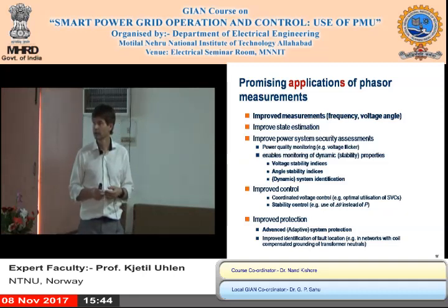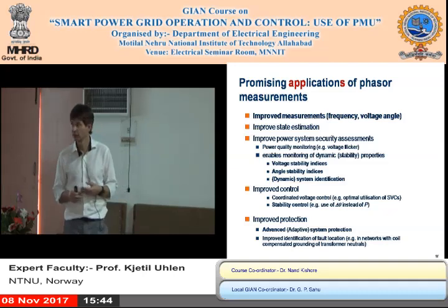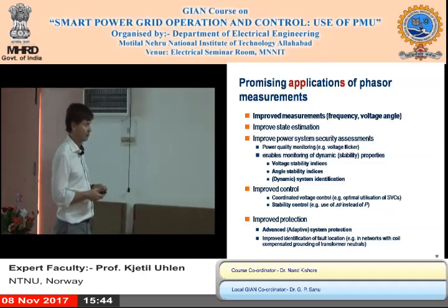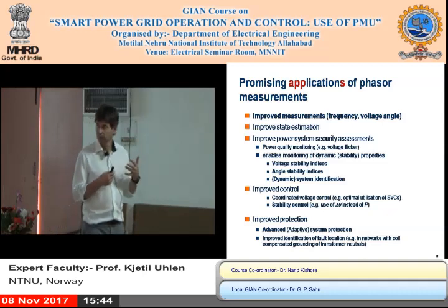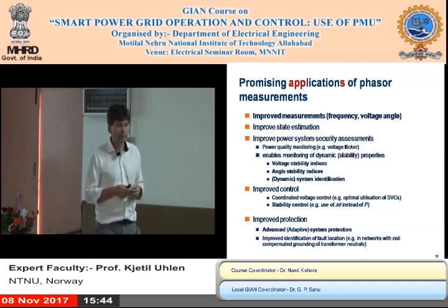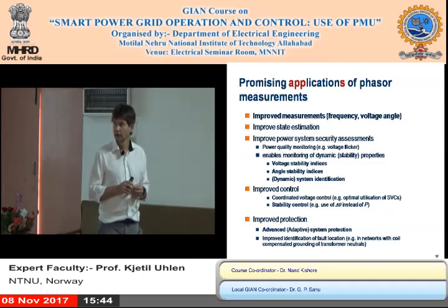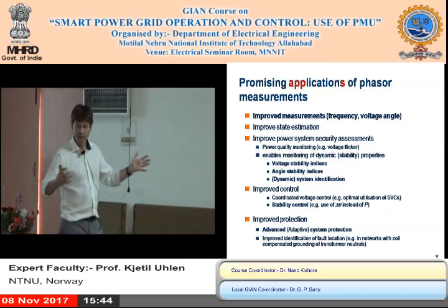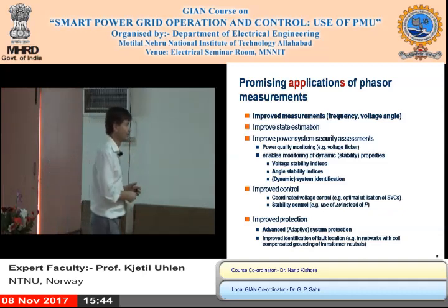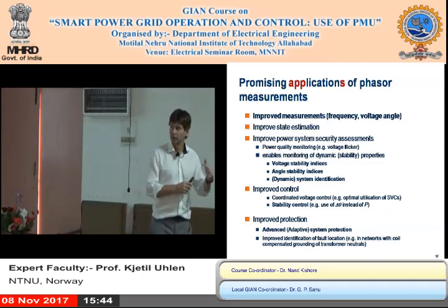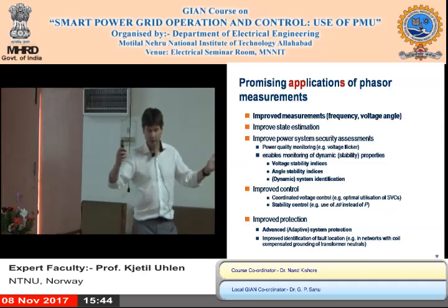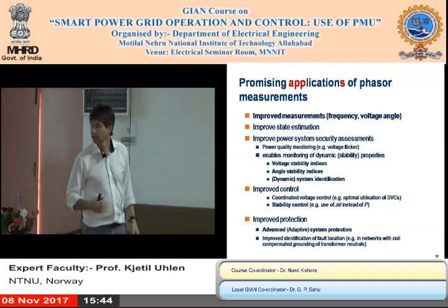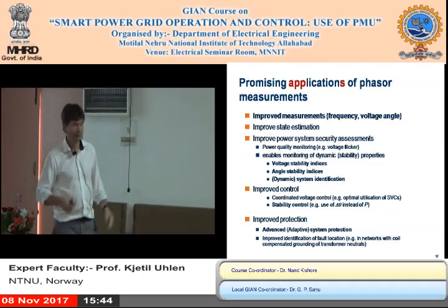And then there are examples of using PMUs for stability enhancement in terms of power system stabilizers or power oscillation dampers. The idea there is that you could utilize the fact that you can measure voltage angle differences. And maybe sometimes that is a better signal than measuring the local power on a line, for example. You get the wide area perspective by comparing or measuring the variation in voltage angle.